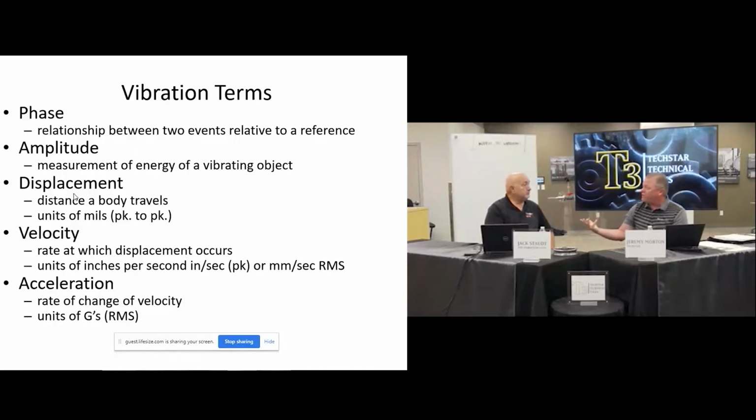Are you able to make diagnostic calls based off of that? Yes, you can. Personally, I like to collect data in line with the shaft, at the bearing locations, because that's the stiffest part of the machine. So you're going to get true readings right there. But with the triaxials, even if you're setting it on top of the machine and getting an inline of your vertical, but maybe not your horizontal, if you're consistent with it, it works well.